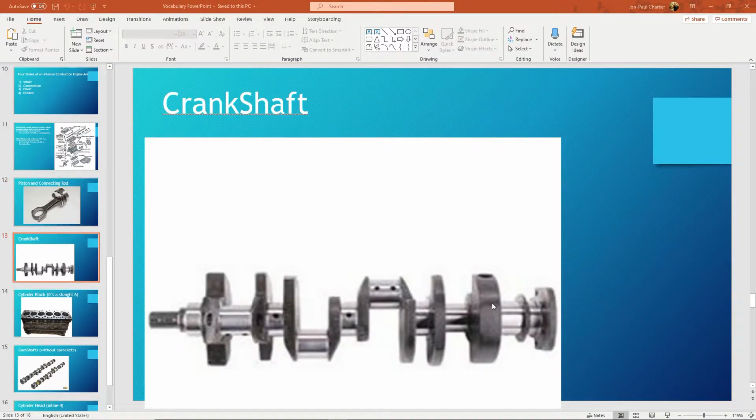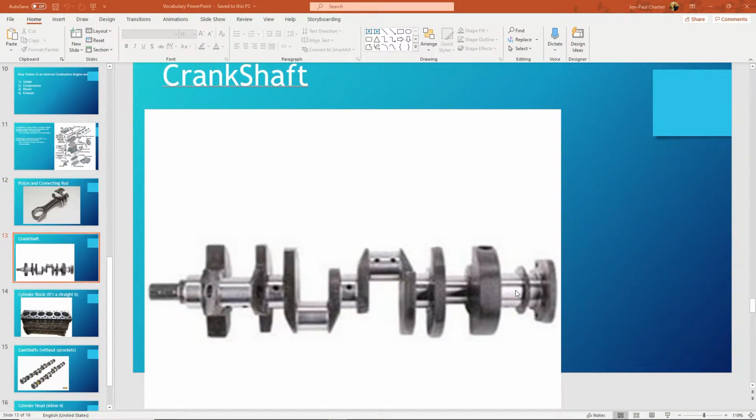But either way, here we have a crankshaft. Please note the common line through the center. We have to have somewhere to bolt it to the engine as this whole elliptical thing rotates. So there will always be a common line. And then that would be here, here. This is where the main caps would go. And then you'll notice here, and it's hard to see, but this one is closer to you, and this one is further away from you.